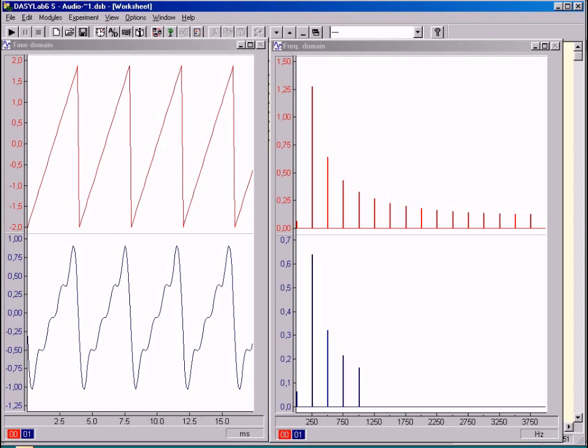The consequence is the extremely important Fourier Principle. All signals can be understood as consisting of nothing but sinusoidal signals of differing frequency and amplitude. The next logical conclusion is: if it is known how a given system reacts to sinusoidal signals of different frequencies, it is also clear how it reacts to all other signals, because all other signals are made up of nothing but sinusoidal oscillations. Suddenly, the entire field of communications engineering seems easier to understand, because it is sufficient to look closely at the sinusoidal signals of different frequencies.